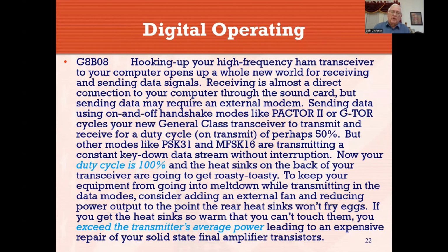The heat sinks on the back of your radio get roasty toasty. I kind of like that term, roasty toasty. So you can either cut the power back a little bit, cut the modulation back along with it, or put a big fan on the back and keep it cool, but you still risk blowing up the final output transistors in your transmitter. You don't want to exceed the transmitter's average output power, which can blow up those transistors.